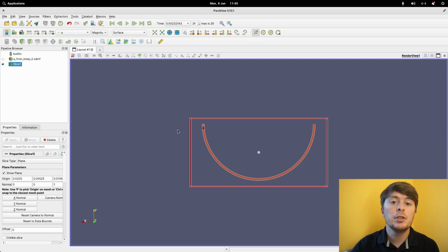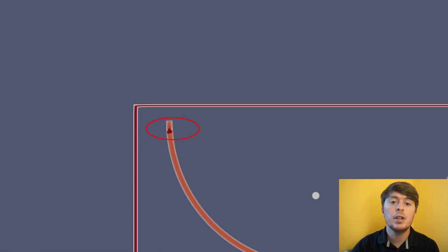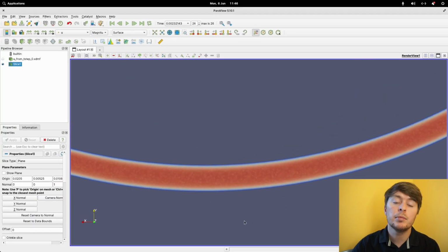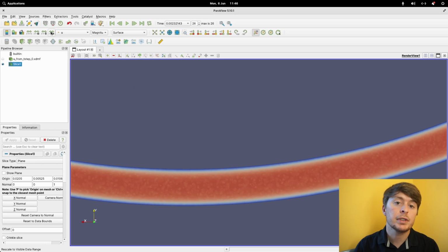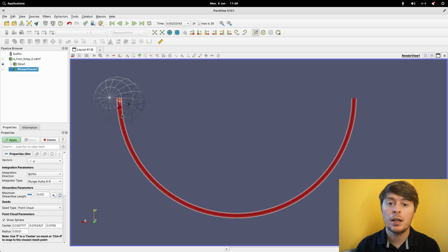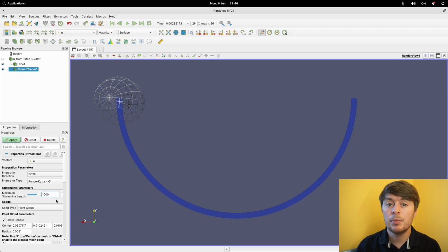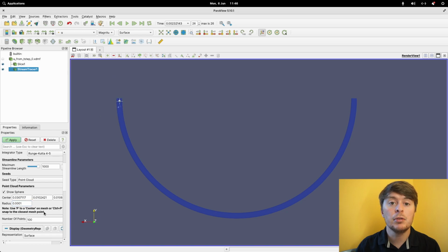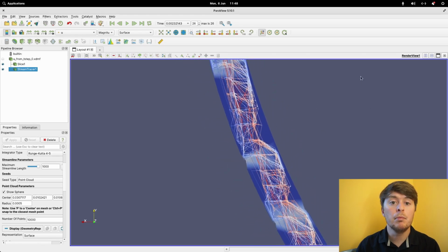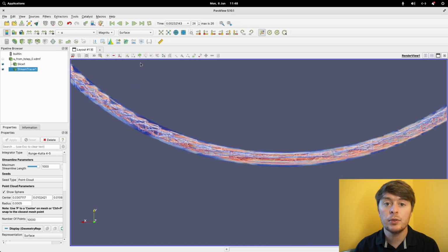In this example, we do see some turbulence at the initial inlet, maybe due to instabilities in our solver, and it becomes laminar across the model. Going further, we can start looking at applying streamlines to this, and we can look at applying further cross sections to the middle here. And because it's a curved channel and it's at the microscale and it's a laminar flow, we may be able to see some Dean drag forces.